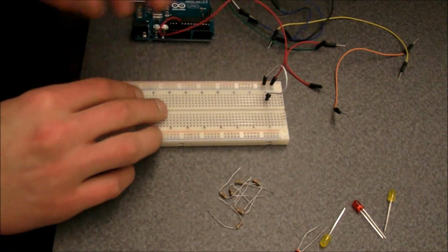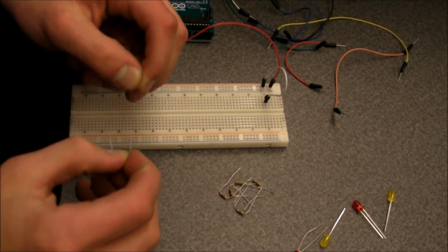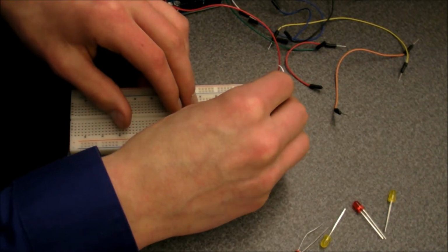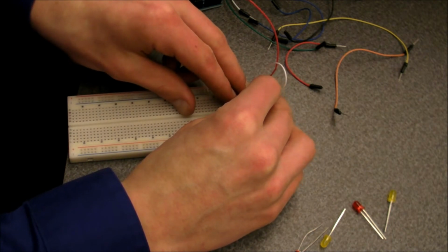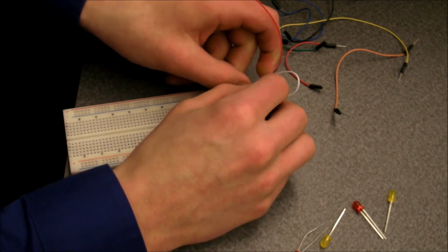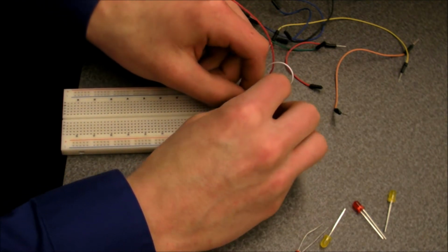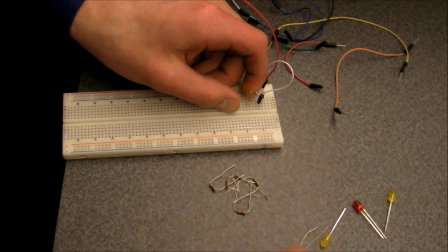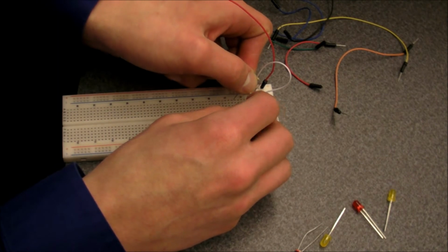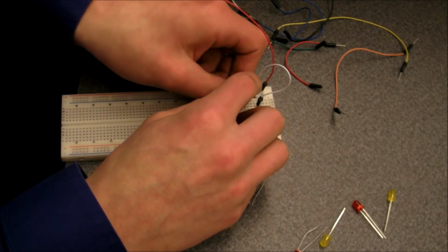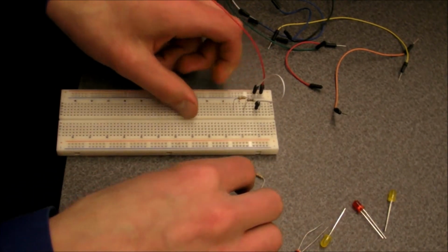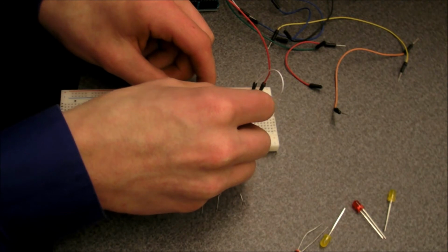like so. And now it's got to go through these 3 150 ohm resistors, and once again these resistors are in series, and sometimes they can be really painful to try and get in, like they are now. Okay, yeah, so these are all in series, and we'll have an equivalent resistance of 450 ohms, as I mentioned earlier. And this will be delivered to the light sensor, just about down